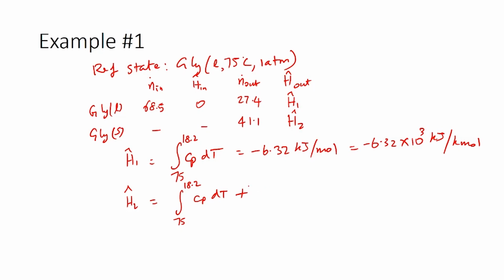Heat of fusion by definition is the change in enthalpy associated with the phase change when solids melt to form liquids. So here we have the other way around, where liquid is being solidified to form solids. So here is a freezing process, which means the specific enthalpy change would be negative of heat of fusion.